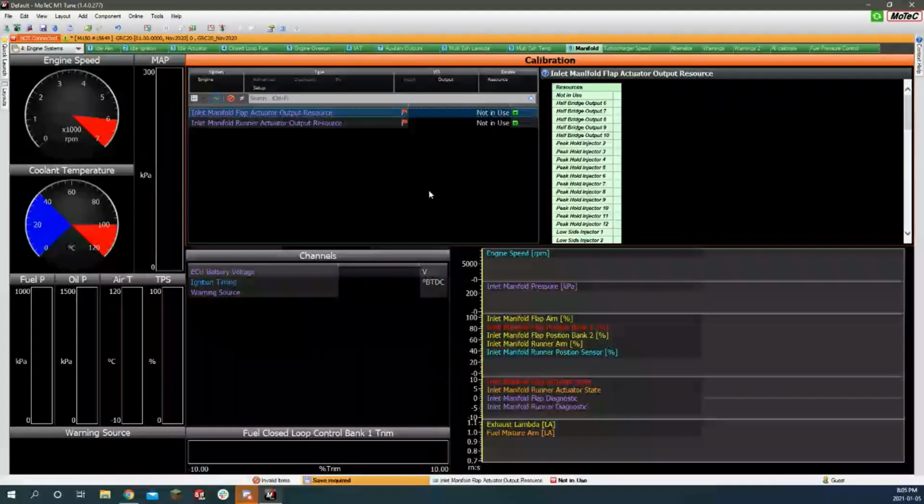This is like what my clips had. Not mine, the higher level versions of it, but some cars have variable intakes, kind of like how VTEC will come on and it changes your valve lift and timing in a Honda engine. You can have a flap that effectively changes your intake runner length to tune for higher or lower RPM, and that can come on at a certain RPM. That'd be how you control that.